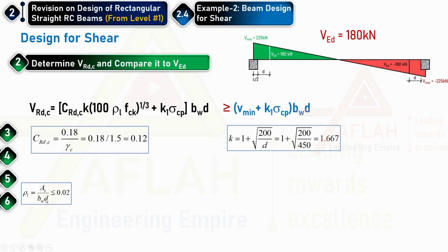AS divided by BWD. Now, since here the reinforcement, we knew that 5 phi 24 is required at the bottom and 4 phi 14 is required at the top. This may go to here and this may go to here. However, the moment was maximum only at midspan and it is going down to 0 at the support, right?